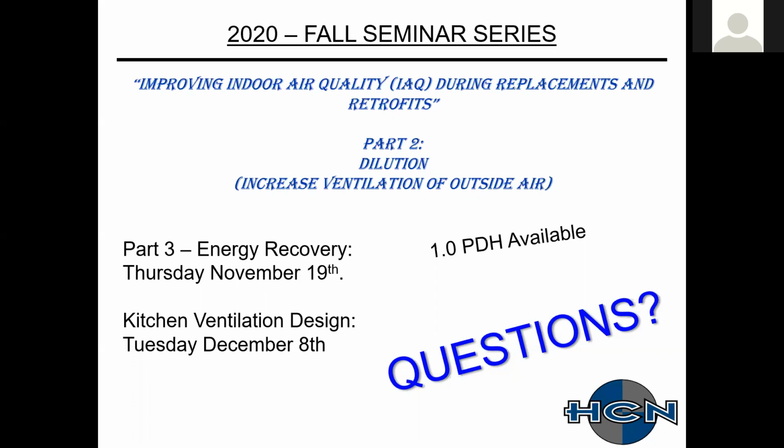A humidifier typically requires obviously a drain pan underneath it. And then the airway length is probably in the range of, I've seen 12 inches up to 48 inches. Obviously, the larger capacities result in a longer airway length. And then just generally would say that the larger your system or larger your equipment, you would have a better opportunity to add humidification versus a smaller piece of equipment. So an example just off the top of my head would be like a 70-ton unit versus a 15-ton unit.